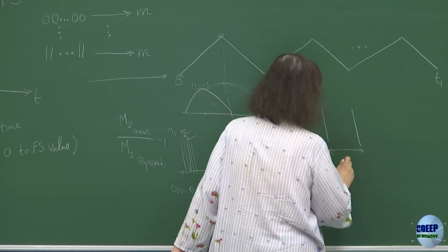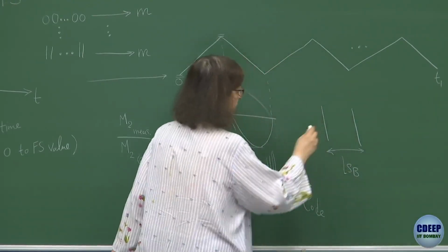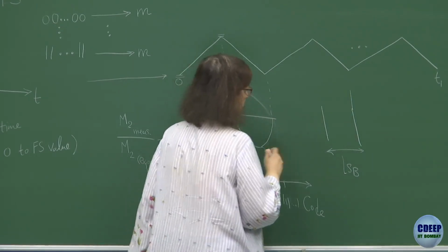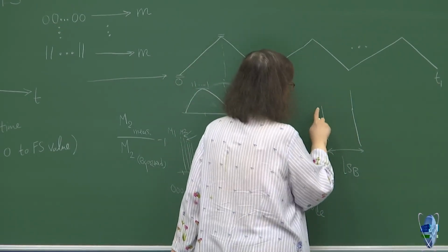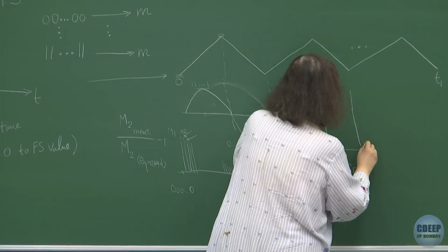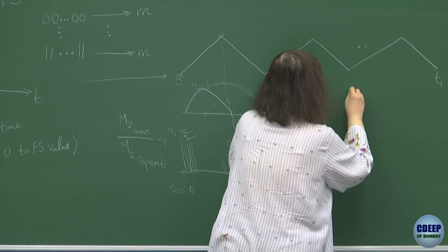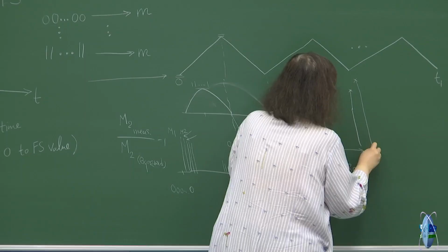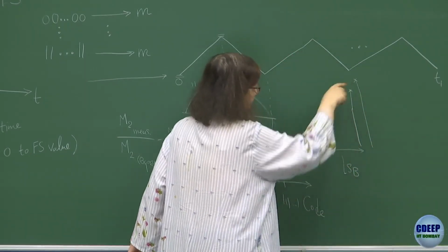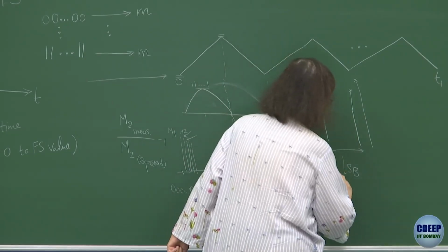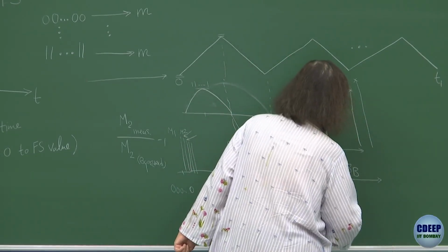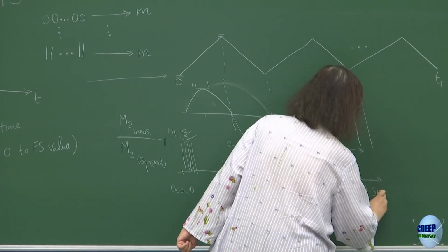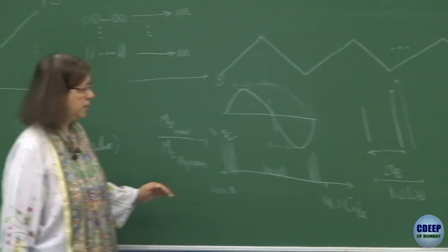If you have one LSB distance between two code transition points in the ADC characteristics, and this has increased by some factor, independent of the waveform, it is equivalent to saying the distance has increased by some factor, say 1.2 LSB.